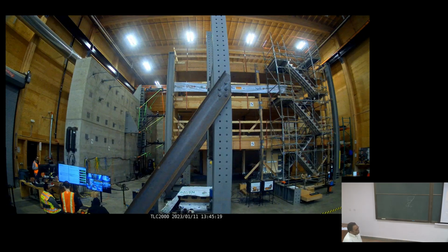You'll see towards the end of the test, because we went back and forth slowly, you'll see a lot of displacement. Keep an eye out for this straight column which was detached from the building, and then you can see the relative displacement. We took the building to 4% drift. For a 30-meter tall building, 4% drift is 1.2 meters, in that direction as well as that direction.